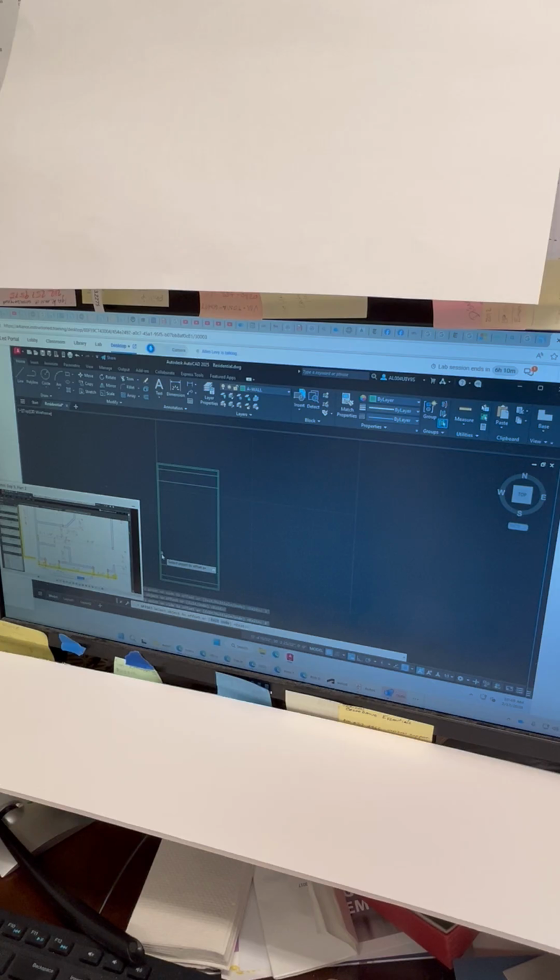Then I'll offset that resulting line 2 foot 6. Then I'll offset that line 6 inches, and then 3.5 inches. Notice there's no dimension for 3.5 because we have an overall note: every wall in here is 3.5 inches thick. Then I'm going to offset this bottom line 2 foot 10, and then another 3.5 inches to get this thickness. So we're going to find out where all of these walls are and the door opening. That's a door opening to get into the water closet.